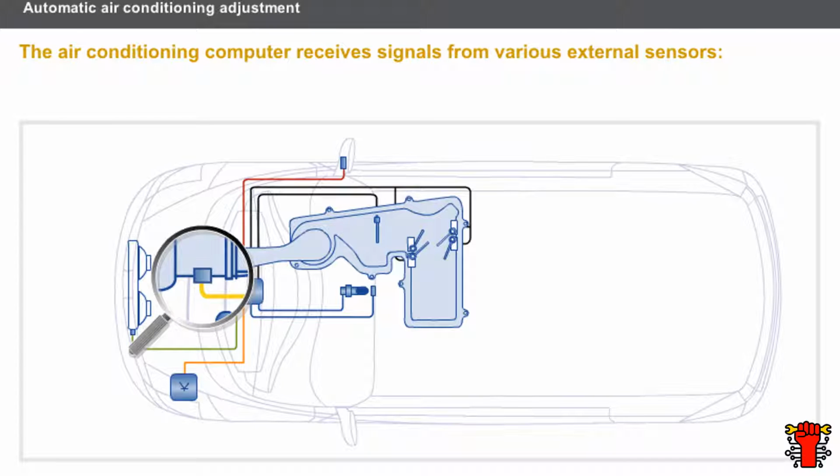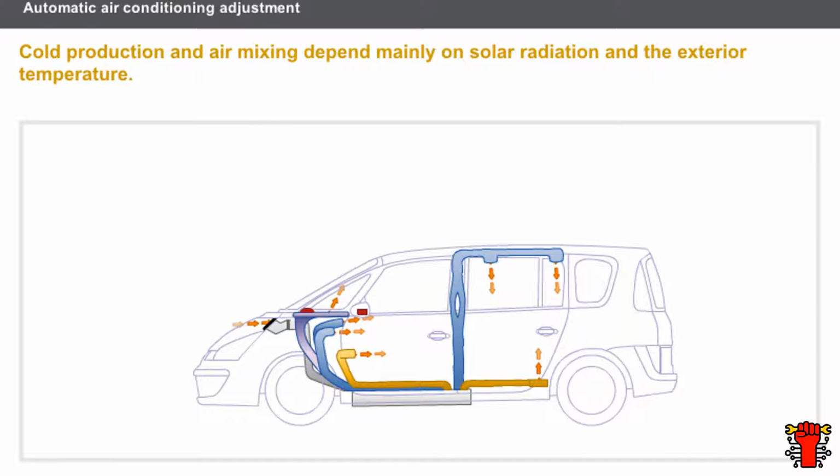The semiconductor-type toxicity sensor is located at the entrance to the air distribution unit. It continuously analyzes the development in concentration of CO and NOx gases and communicates them to the computer. The sensitive component in the toxicity sensor is protected by a membrane which blocks humidity and dust but allows gas molecules to pass through.